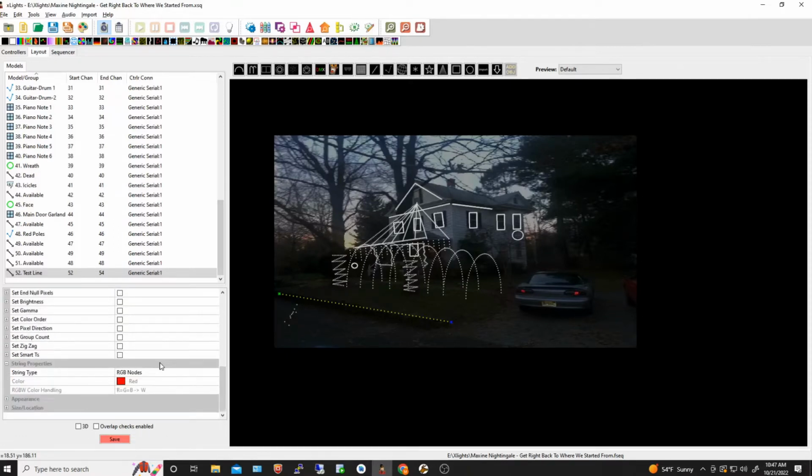This is a little bit kludgy going on here. Now, string type. Notice how it goes 52, it uses up start channels 52, 53, and 54. But I'm really sending a byte controlling a string that's going to turn this string on and off. So the problem is that if it's like an RGB, which I do have in these arches on my house, those are 3 different channels on a board that I built that I don't want controlled through here. I'm going to control everything through my Arduino.